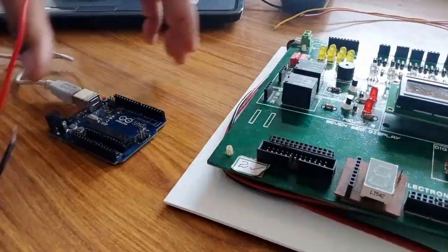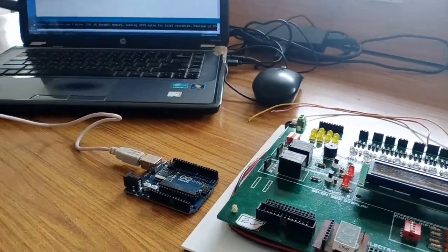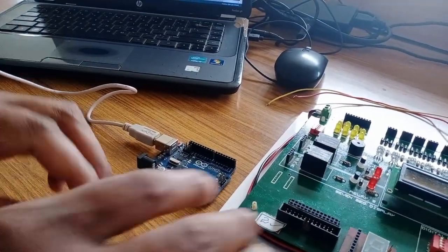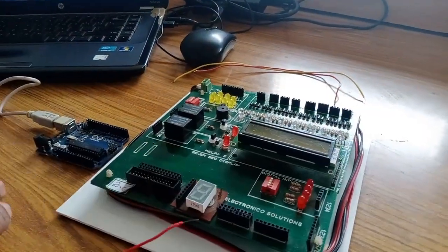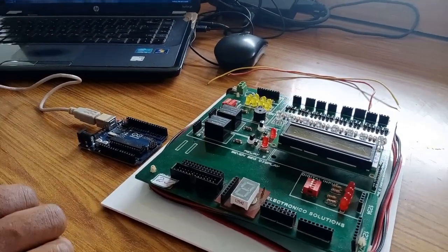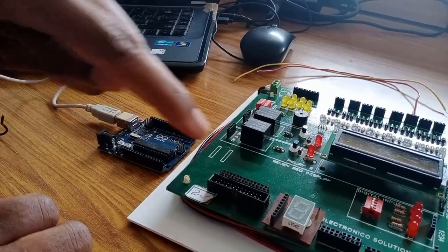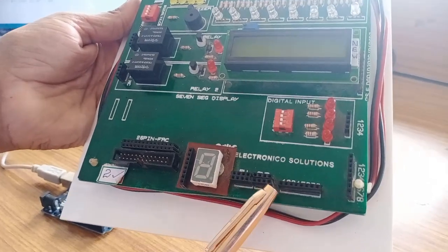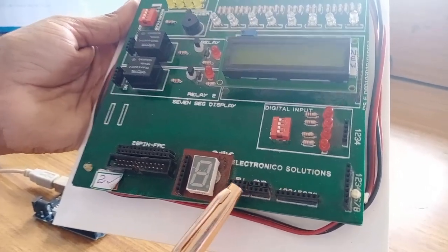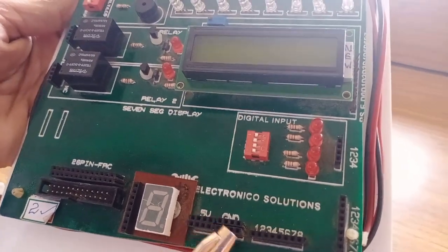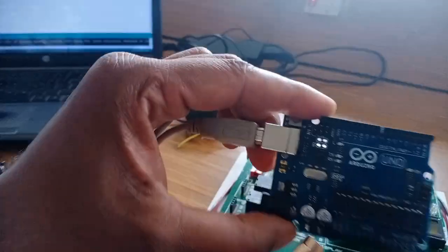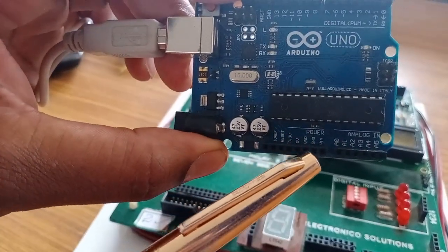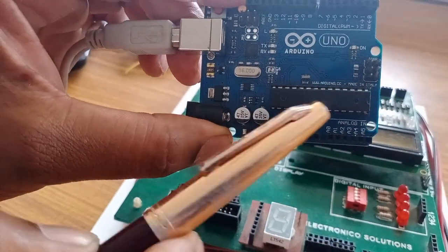You can remember how we started giving the simulation hardware connection. First of all, what we will do? We will power our IO board. In our simulation, we powered our breadboard. Here we need to power our IO board. Here you can find 5 volt and ground. These two are power pins. From where we will get the 5 volt? Here you observe, you know the Arduino power pins. From the power pin 5 volt and ground, we can power our IO board.